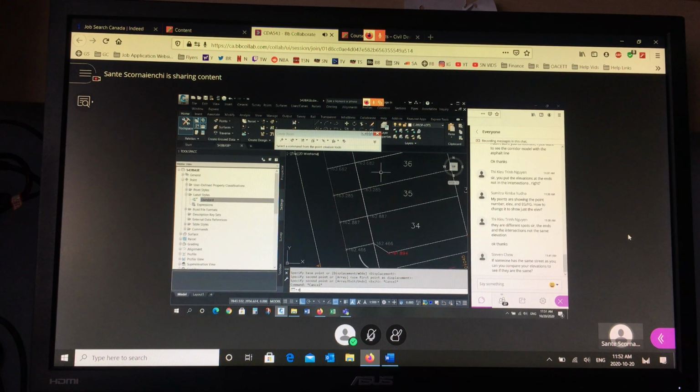I'm going to move these points. This you can do all at once. This is a global command. Move this point, this point, this point, and this point. Enter. It's asking me for a base point down here. The base point, I'm going to start at the origin. 0, comma, 0, comma, 0. Okay? And from that point, where am I going to move these points?